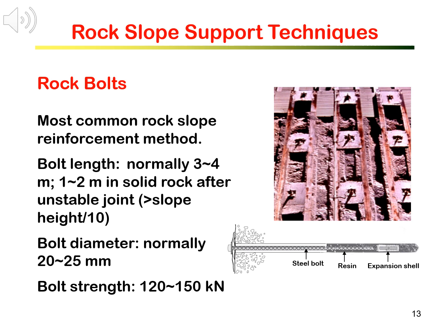Design of rock bolt lengths can adopt the analysis of unstable block size or use the rock mass classification system. In other words, we will need to estimate the size of potential unstable rock blocks and the wedges, and then decide the bolt length accordingly. For systematic bolting, we can estimate the block size from joint spacing from geological mapping.